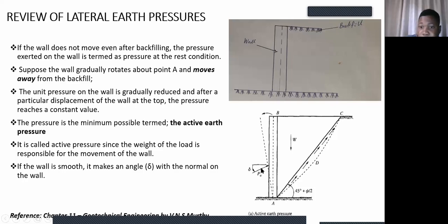Now, obviously, there's a free body diagram here. You have your retaining wall, causing this deflection. This is the short dashes I do here. Now we're trying to draw the free body diagram of the effect of that backfill. You may want to ask me why I am putting the arrow on the other side. Always remember that the line of action of a force is continuous, so me putting it here does not really matter. What actually matters is that I'm representing what is acting on this body, and I also indicate my rotation aspect, that it is moving away from the backfill, and that is the cause of the discussion: the backfill is making it move away, and the weight of that backfill is what is causing that rotation. Hence, it is called active earth pressure.